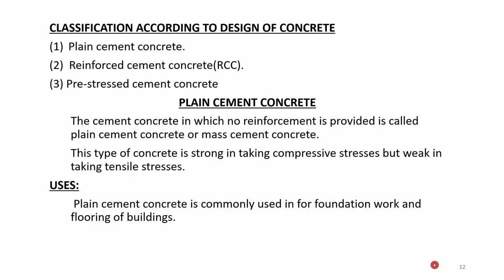So when tension is happening in the structure, the concrete has to be reinforced. Pre-stressed cement concrete is also a new technology where we are stressing the cement concrete before applying the load. So once you load the structure, it will initially be in compression, and it will have lesser tensile stresses.